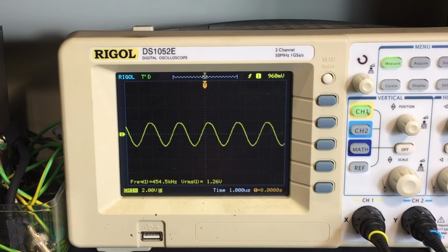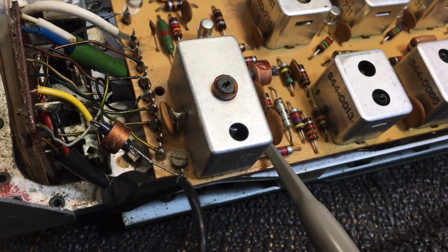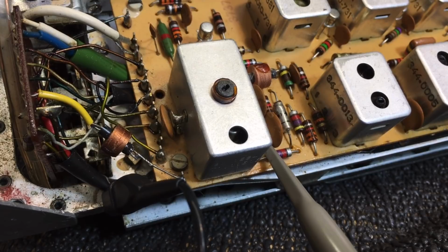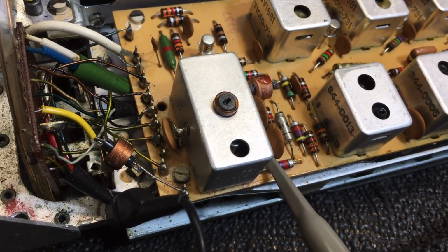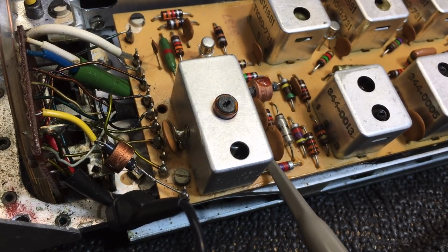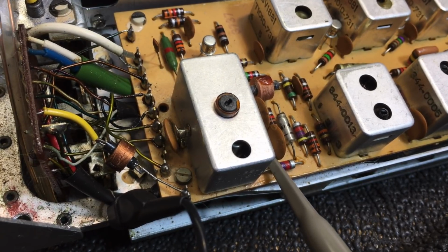I'll do the fine tuning once I put the cap on. I've got to put that cap on because this thing needs some shielding, but it seems to be fairly stable. Brilliant. One dead transistor, probably leaky. Okay, let me put this together and we can try and tune it. There we have it, we've got it back. You have to bend that capacitor back into place, make sure it fits. It's a tight fit. And I've soldered the ground lugs on the sides again.